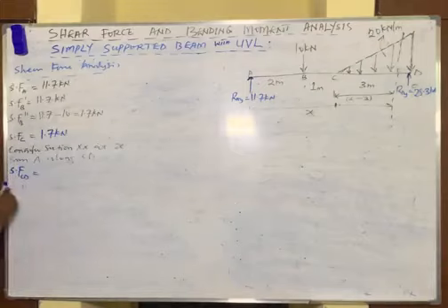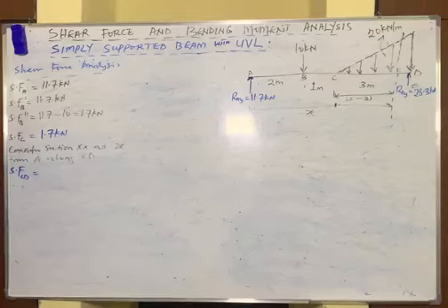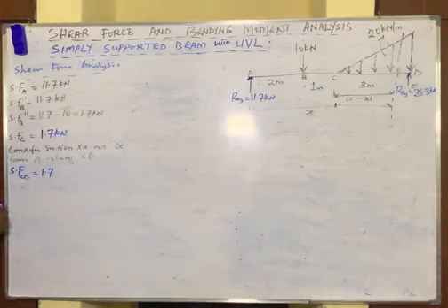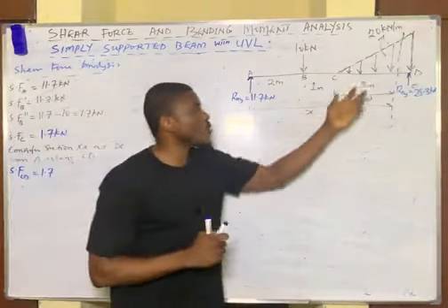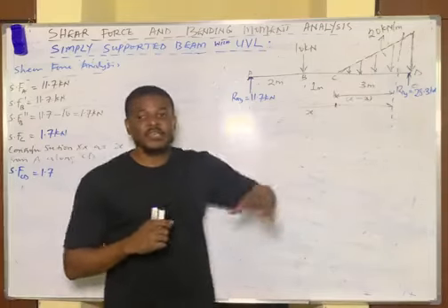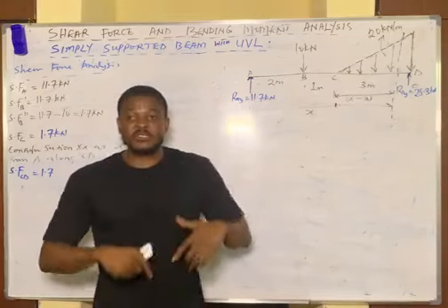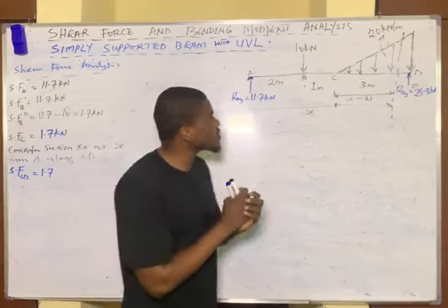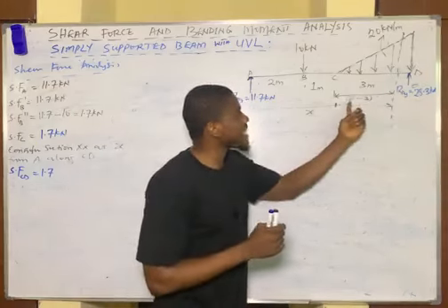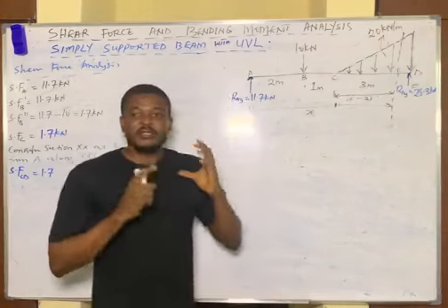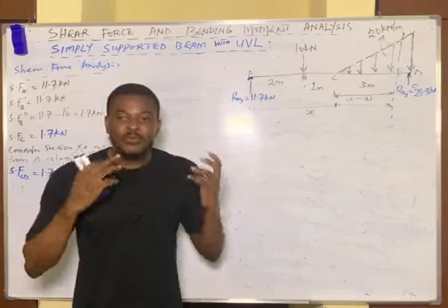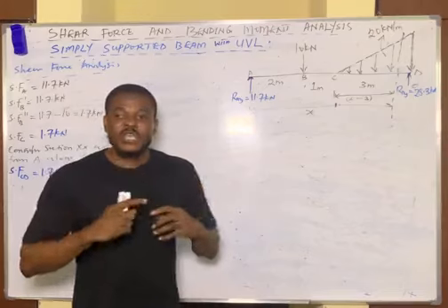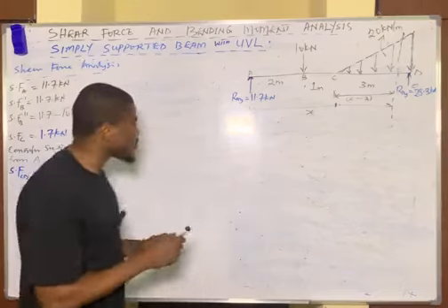Now you find the shear force CD. This is going to be equal to, so remember, this 1.7 kilonewtons force moves initially, so you put it down, 1.7 kilonewtons. Now, since you know that the UVL is always acting downwards, its force is going to be negative because it's acting downward. But now the UVL has a new length. We are considering the length of the UVL about the section, which is x minus 3. And remember, we have to convert this UVL to a point load first. Since we're talking about shear force, you have to convert it to a point load.